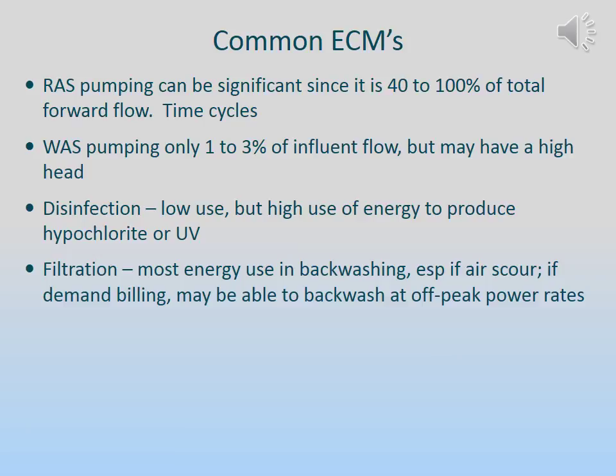Time cycles are not appropriate with a single pump and clarifier, but are an option with multiple systems. This way, sludge can be continuously returned to the process.